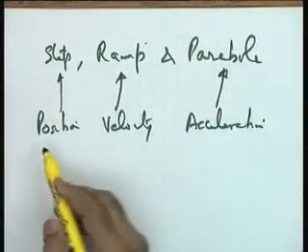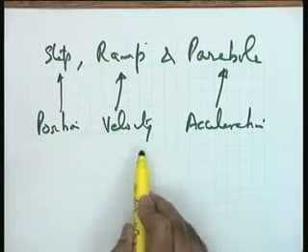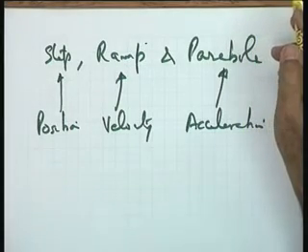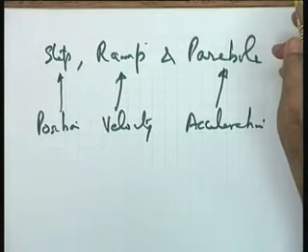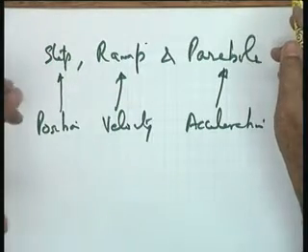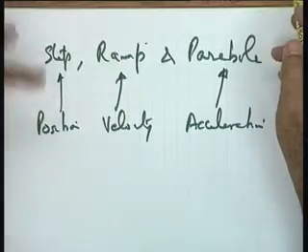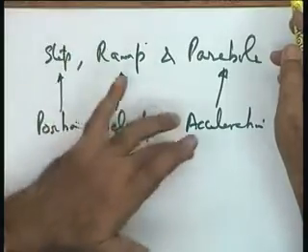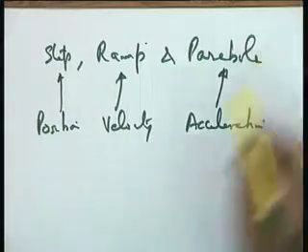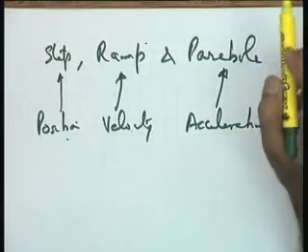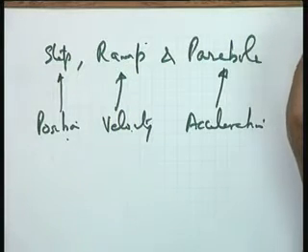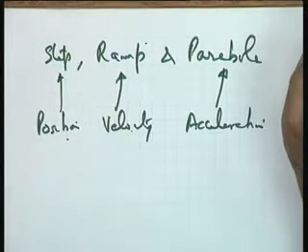But the meaning of the words position, velocity and acceleration will change if your system is, let us say, a temperature control system or a liquid level control system. Still, if you don't confuse yourself, then in that particular case the words position and step, velocity and ramp, acceleration and parabolic could be interchanged. Keep in mind that these also are functions, and mathematically they are given by step, ramp and parabolic. So we will go ahead with the terms used in the literature.